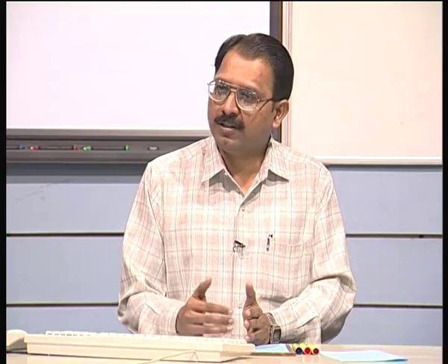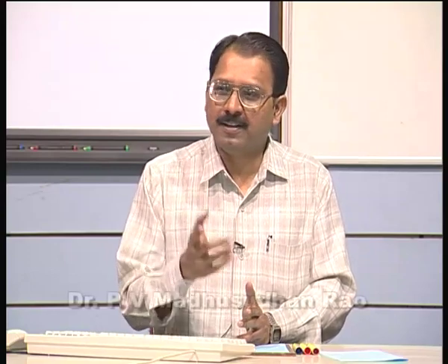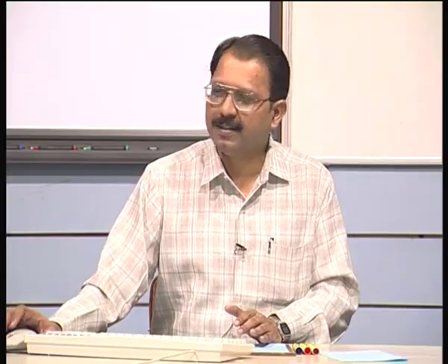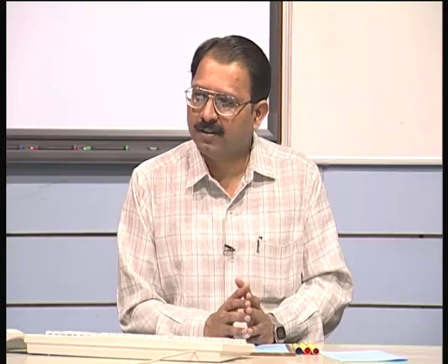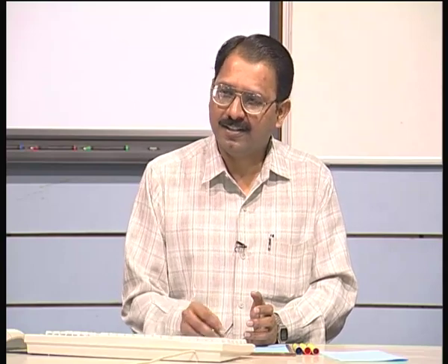How will I do it in, let us say, an octree based method? You first see what all the cells are. Cells may be of different sizes. Suppose I am calculating area, I can look at different cells which have different areas, count them, add them, and then you get it. If I have a voxel based model, all you need to see is what the cells are, add all the cells and just multiply by the volume of a cell. So, a little more convenient in this respect.